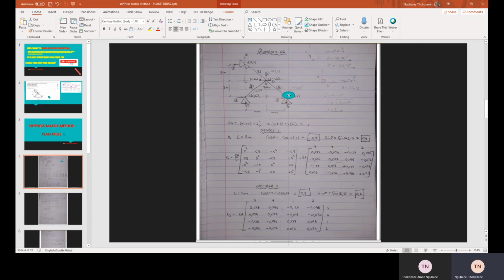I don't need the angle inside actually, I need this angle here, but on a straight line we know that angles make 180 degrees, so 180 minus 36.86, we got 143.13. If every triangle here is similar, then this angle is equal to this one. So on the side I need this angle, which is 36.86, and for member 1 I need this angle here, which is 143.13, as I got it here.